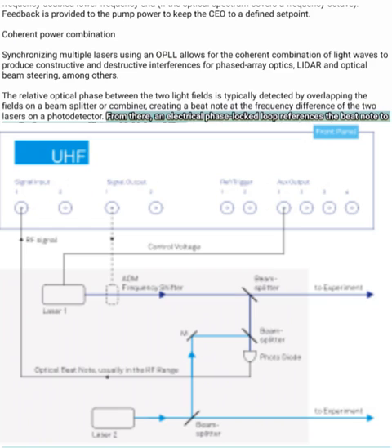From there, an electrical phase lock loop references the beat note to a radio frequency oscillator with high stability. The feedback signal is then fed to a frequency or phase shifting element within the setup. The latter can be an element inside one of the lasers or an external element such as an acousto-optical modulator. Measurement strategies. From a signal analysis and control perspective, the examples above can be readily understood by replacing the complex details of the optical setup with a voltage-controlled oscillator, VCO.